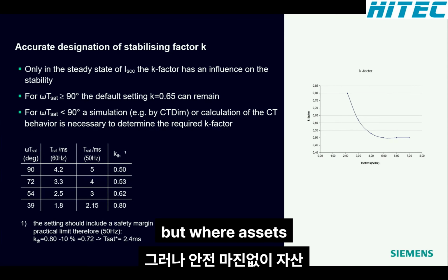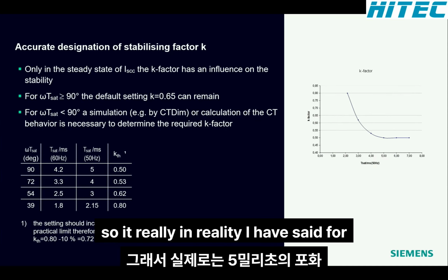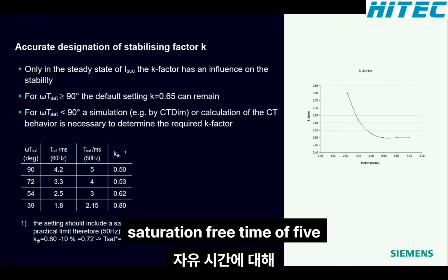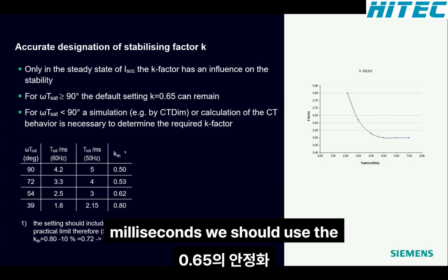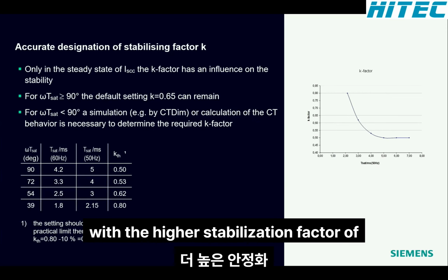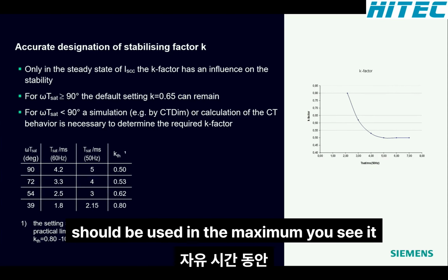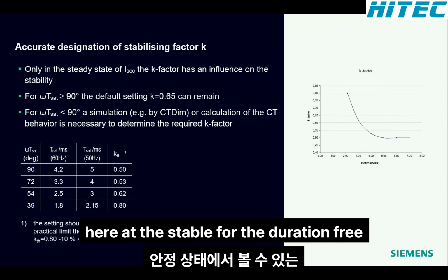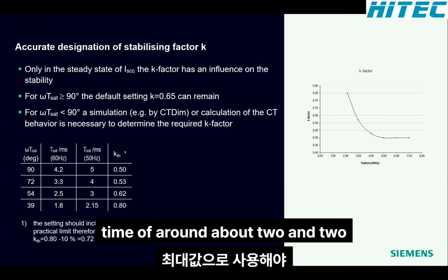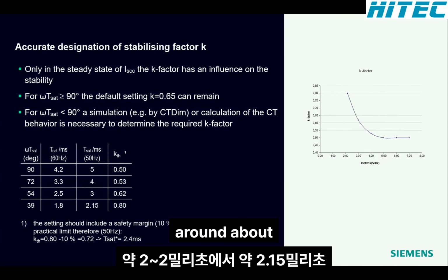But that's pure calculation without safety margin. So in reality, as I have said, for a saturation-free time of 5 milliseconds, we should use the stabilization factor of 0.65. And even the higher stabilization factor of 0.8 should be used at the maximum, you see it here in this table, for a saturation-free time of roughly 2 to 2.15 milliseconds.